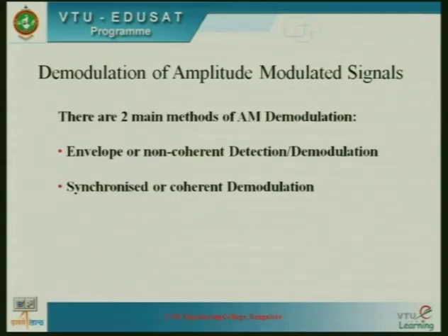As we were discussing, there are two kinds of demodulation techniques: envelope detection and synchronous detection. In envelope detection, there are two different techniques to be understood. One is based upon the diode envelope detection logic. The second one is based upon your square law model. In both the models, the signal that is coming from the channel is directly fed into a demodulator. The diode and the corresponding resistors and capacitors are able to extract the message.